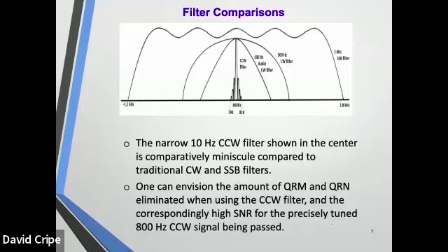This is just a quick diagram indicating, again, a regular standard SSB filter bandwidth. And the filter bandwidth on the next inside would be that for a CW filter, roughly 500 hertz. Maybe crank that down to 100 hertz. But there in the middle is the 10 hertz filter that one is able to receive with a 12 words per minute code speed of code that's coming at you.